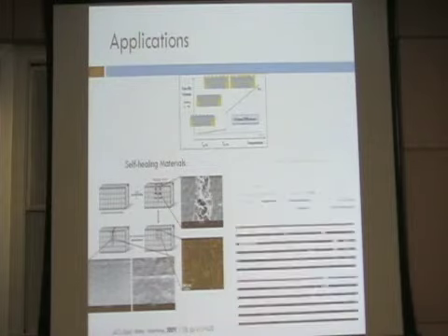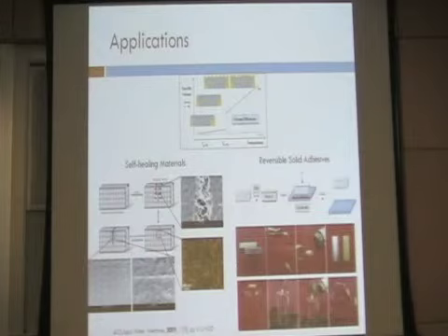And also, we know that the thermoplastic component, PCL, is a very good hot melt adhesive. Once the material is heated, all the surfaces are covered with a thin layer of PCL, so we can use this material as an adhesive. It's a very unique adhesive because it has a high degree of structural rigidity in the adhesive state. And the adhesion comes from the crystallization of PCL, so we can easily go above its melting temperature to break the adhesive bond. So that renders reversible adhesion to our material.